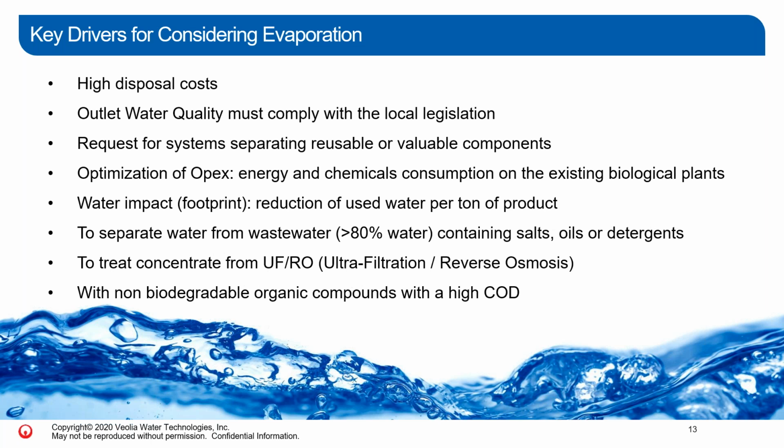But the point here is if you have a high disposal cost, you could have a very concentrated wastewater stream. It may be difficult for a biological system or a traditional physical chemical system to deal with. But just because you have a smaller volume doesn't mean you're going to pay a lower fee, because you do have those high concentrations. Or if you have a medium volume that you're just looking to reduce. So that's one area where evaporation is going to be a good technology to look at.